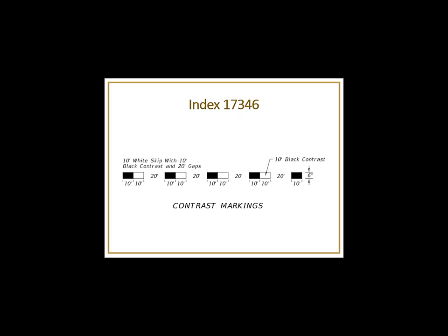this option. The option with the 1.5 inch on either side was spelled out with a pay item. It had its own pay item number as 9 inches wide. So when engineers specified that 9 inches, contractors no longer had the option to choose. So that option was restricted to only 2 manufacturers. So that is one of the reasons we selected the trailing contrast marker. The other one is that we felt like it provided more visibility at greater distances. The 1.5 inch contrast was fine for short distances, but when you're looking at long distance, you really didn't even see the contrast.